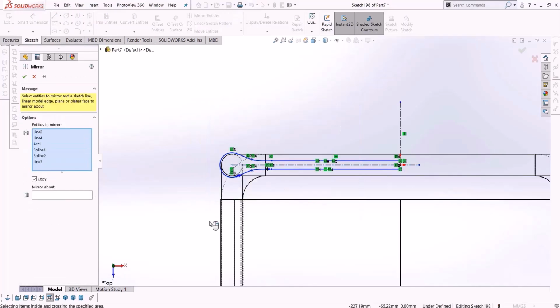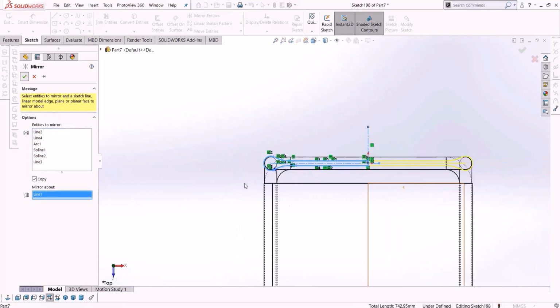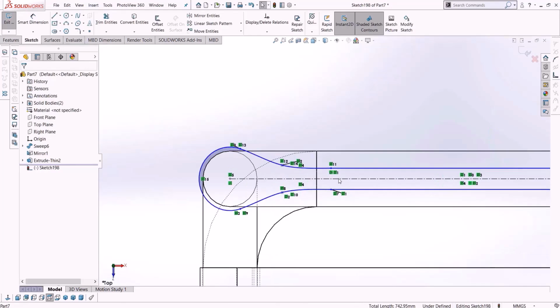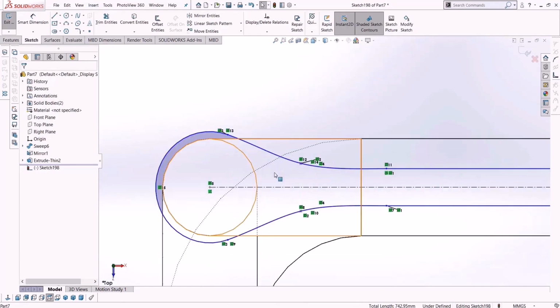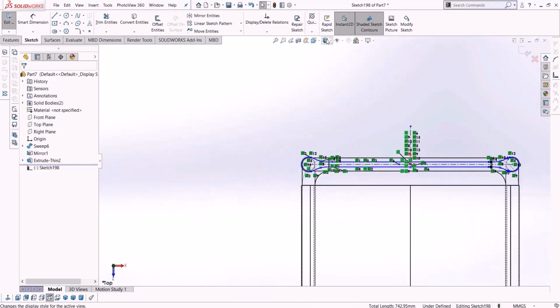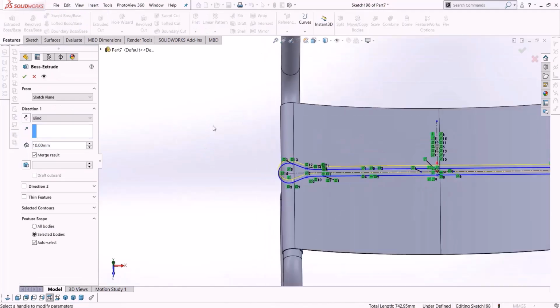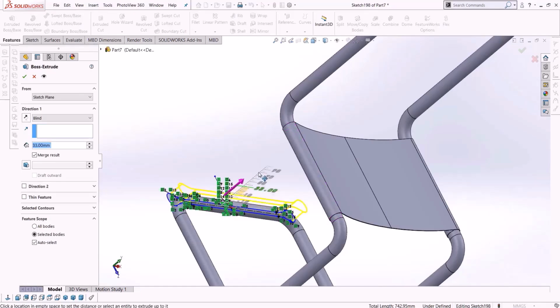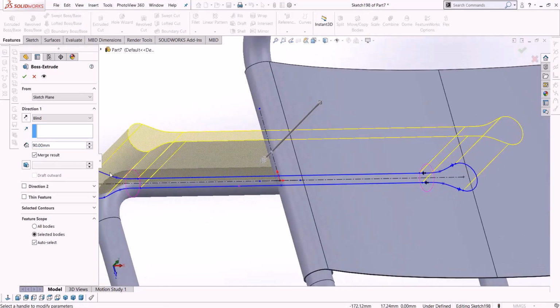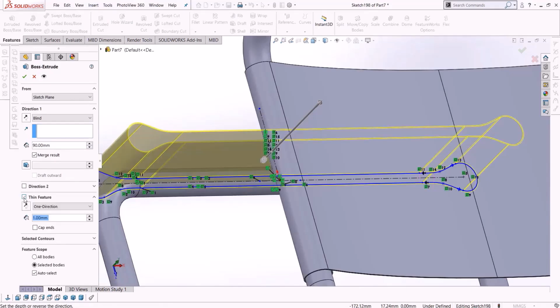Now, it's true that at the present moment, this represents a closed sketch. And if I click on extrude right now, it will extrude into a shape such as shown here. However, at this juncture, the thin feature option can actually be turned on for us. In its previous state, it was always off, meaning you couldn't use it because your sketch initially had no end. It wasn't closed properly in any way.